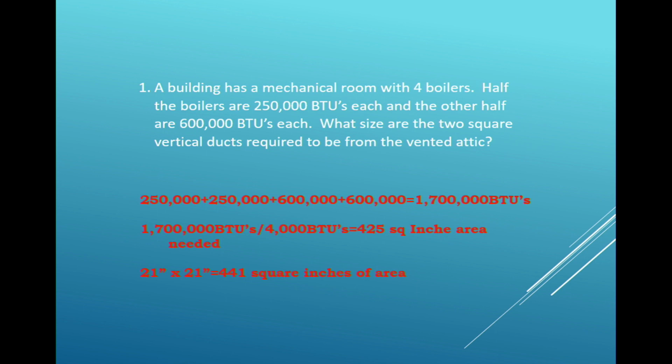It wouldn't be any harder. I just may not be able to do these as fast in my head if it was a 15 by 15 or a 20 by 20 or a 25 by 25 or a 30 by 30, right? I would just work through those one at a time until one of them gave me the size I needed. And then how many of these 21 by 21s do I need? 2. One within 12 inches of the top, another one commencing within 12 inches of the bottom.